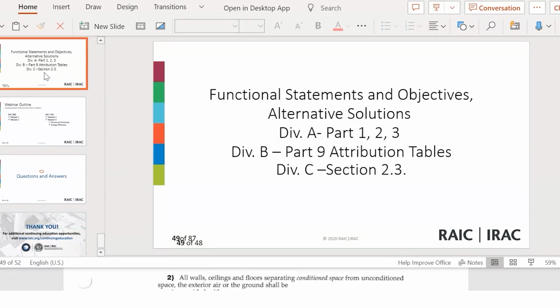So know your major occupancies, know the construction of the building and what the client wants, and then determine, based on what you are designing, the heights, areas and grades, so you know what you're dealing with in terms of floor area, heights of buildings and number of stories. From there on, look at what other fire protection systems are required, and what your exterior exposure is. You'll be working with the mechanical and electrical engineers, right?